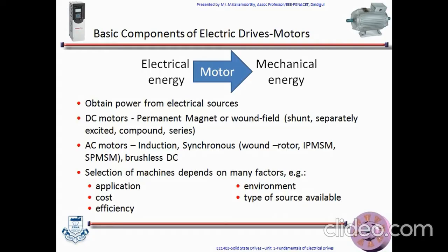Environmental factors also affect the motor type. For example, in environments like petrol bunks, where the environment must be free and clean from arcs, DC motors cannot be used unless they are encapsulated. This is because of the electric discharge that is generated between the brushes and the commutator segments. In those cases, a squirrel cage induction motor or other brushless machines are probably the better options.